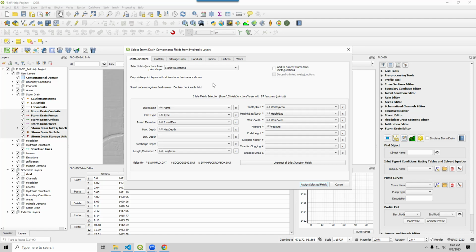to do this very carefully. So most of these will be almost correct, but we don't need everything. So name is okay. The type is okay. And again, Flow 2D or storm drain types are 1 through 5. And we talk about that in the inlets and nodes video.